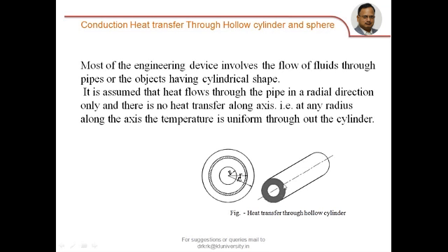Next, what is the temperature here? 100 degrees centigrade. The temperature here is also 100. Here also 100. At this point also say 100 degrees centigrade. That means all along the length of the cylinder, the temperature on the outer surface is the same, which means I am not considering the variation of temperature in the Z direction.